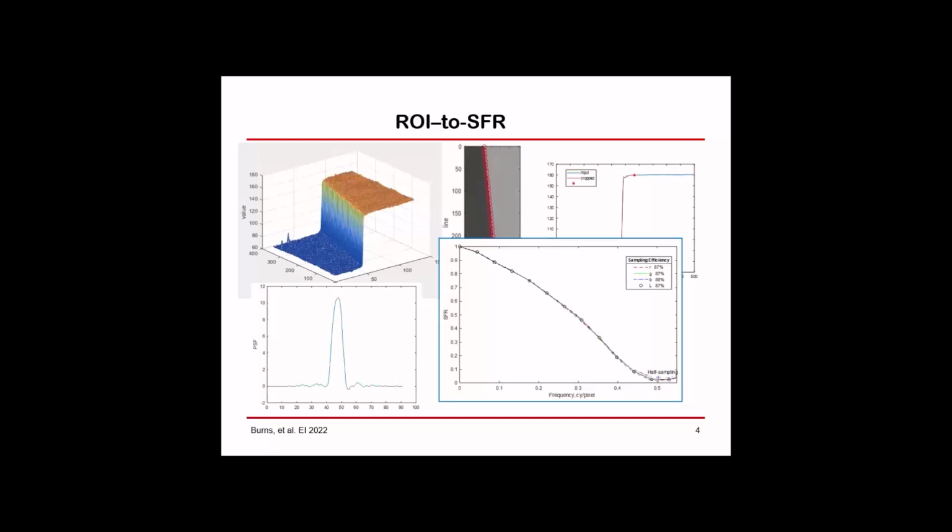The original standard referred to just using a luminance-weighted SFR. Currently, we use the red, green, and blue. There are many applications of this method, including looking at color registration, measures for limiting resolution, and single measures like the sampling efficiency or the 50% SFR point for tracking and quality assurance.